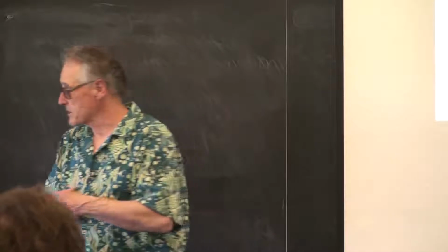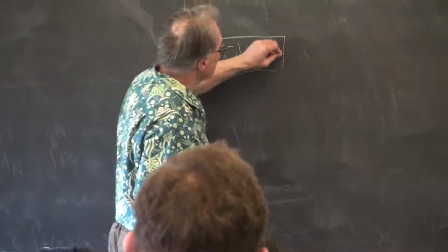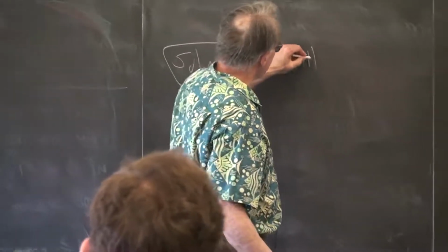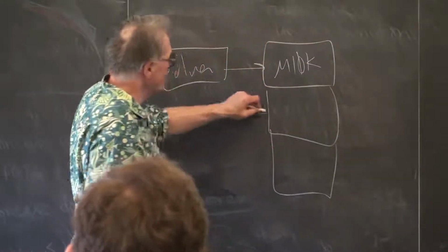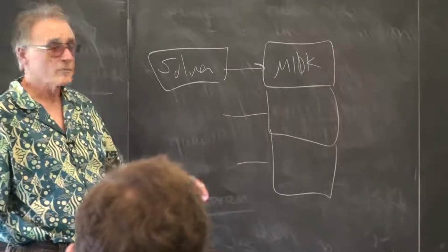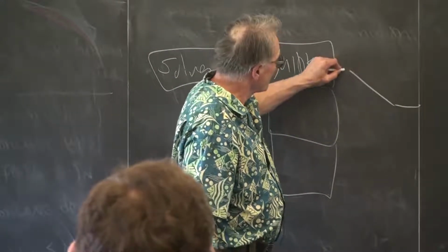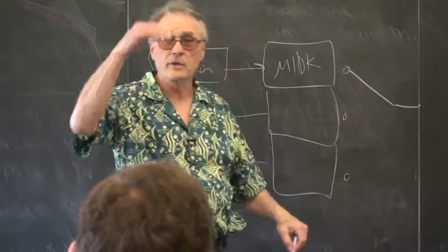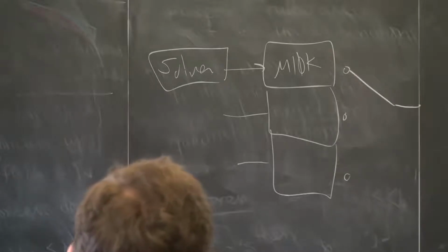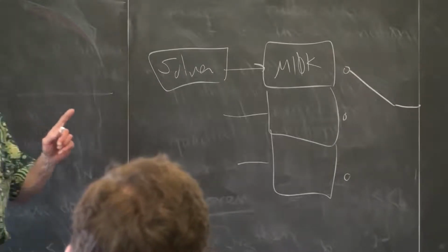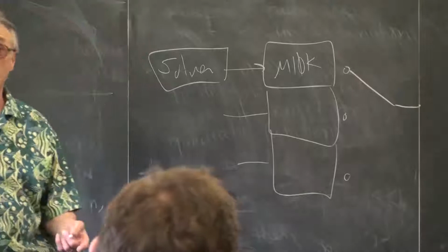So there's a scheme where you have a solver which goes to an M10K block, each solver has its own M10K block. And then the VGA controller at plotting time multiplexes between the different blocks to print the screen. So there's never a serial bottleneck. Well, there is a serial bottleneck, but it's dependent upon the VGA refresh time, which you can't change. Okay.